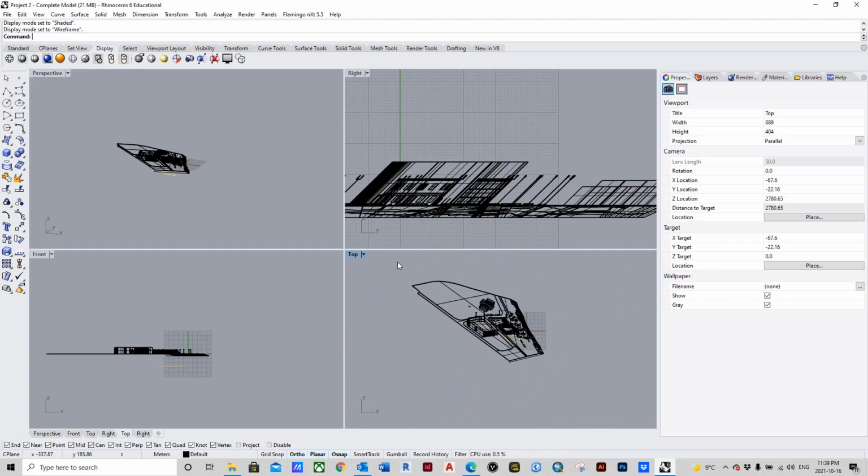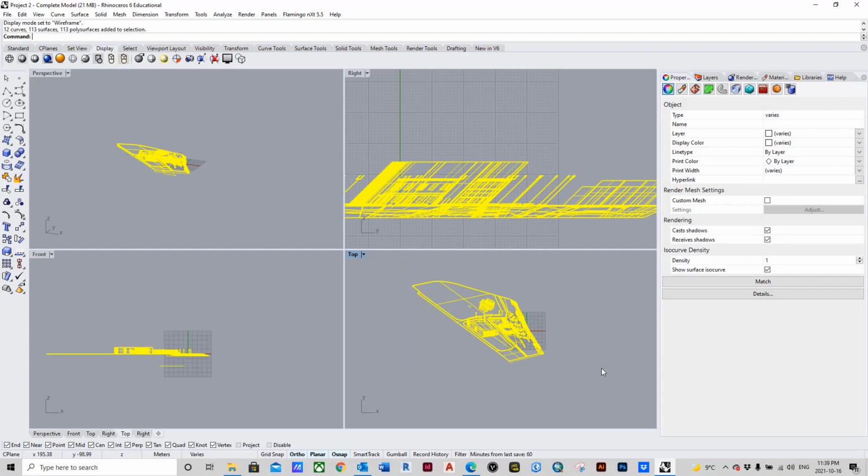We're going to select everything, hold down a left click and drag. And we're going to use the same tool that we've used the last couple of times anytime we've wanted to take a Rhino image and make it so that it is adaptable into AutoCAD. Turn it into AutoCAD lines. So we're going to type, you guessed it, make 2D, M-A-K-E, 2D. Then we're going to hit enter.